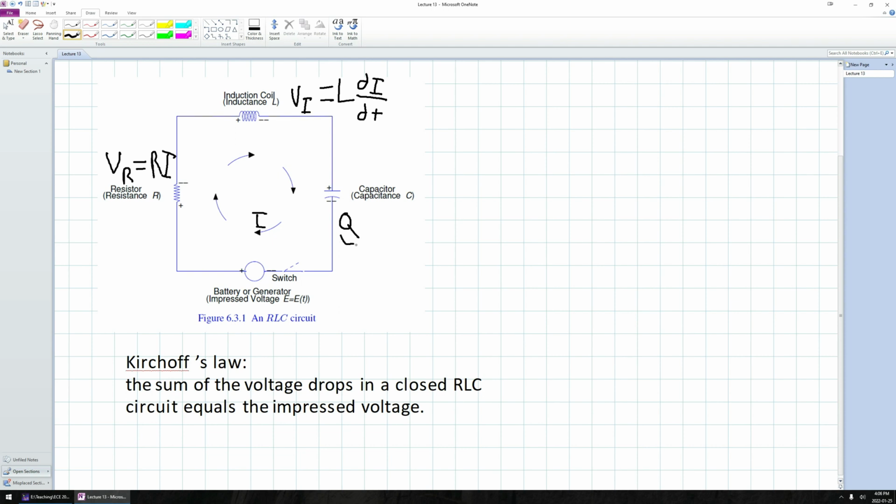Well, if Q is the charge, then once I turn on the circuit by closing the switch over here, the charge of the capacitor will simply be given by the original charge, say at some fixed element of time that I'm going to call t equals 0, plus the total sum of the amounts of energies that get absorbed by this capacitor from time equals 0 up to t. Okay, so what's the energy that gets absorbed by the capacitor? Well, it turns out that for any infinitesimal element of time, the current that gets absorbed is given by this I. So here I could just do I of tau d tau.